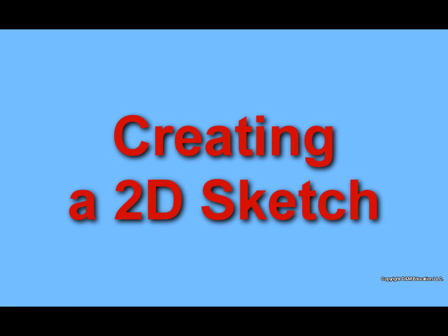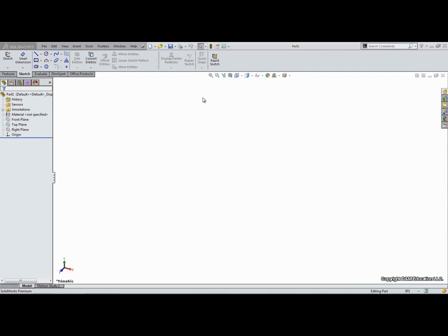In this video, the basics of creating a 2D sketch in SOLIDWORKS will be covered. To start, open SOLIDWORKS and create a new part. Before you begin creating a sketch, it is important to set the units, precision, and drafting standard for the model.